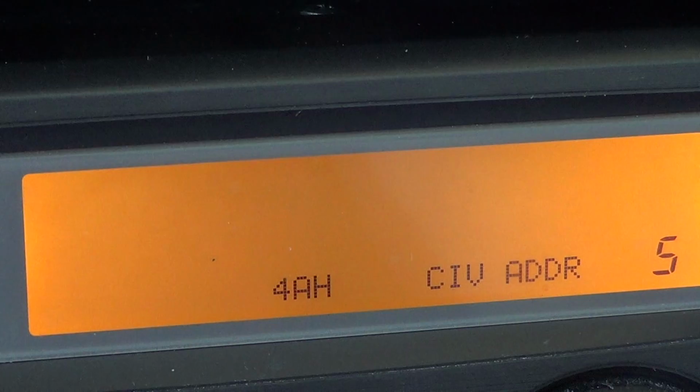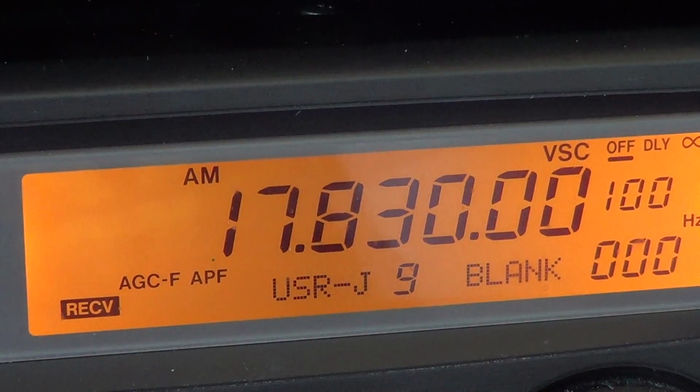So review this video again if you have missed out on something. Keep in mind that at the end of this video you should have a piece of paper with 3 pieces of information on it: the COM port of your computer, the baud rate of your radio, and the CIV address, which is 4AH in the case of my Icom. Once that is done, you can close your radio and power it back on. You know the settings are right.